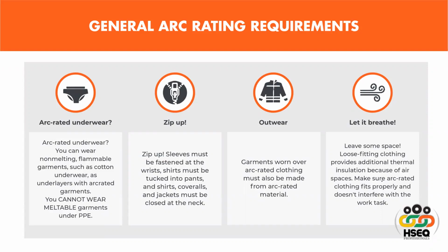For example, if I'm using an arc rated clothing of 12 cal/cm² as tight fitting clothing, versus using the same 12 cal/cm² as loose fitting clothing, that same 12 cal/cm² suit can provide me protection against 14 cal/cm² or 15 cal/cm² of incident energy as well.